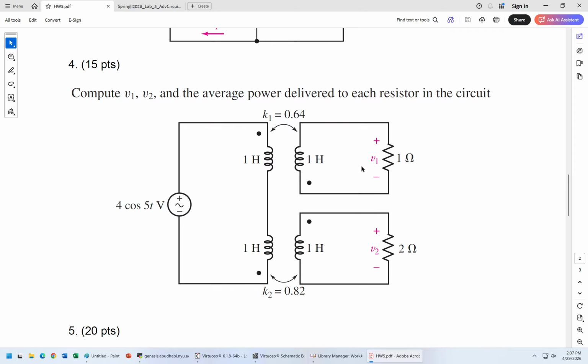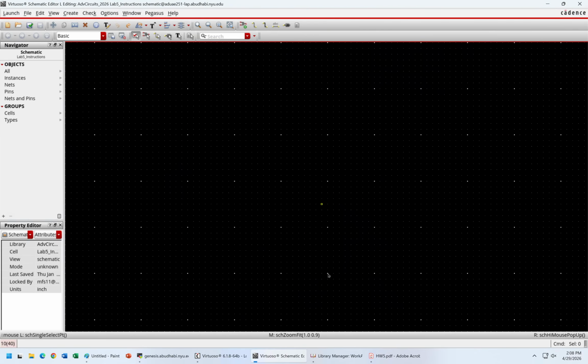You will see how we will always be finding out the voltage across a component instead of putting a lot of grounds, because grounds, as I've been telling you guys, are kind of short-circuiting some of the nodes, which are called reference. You will also see how inductors, when defined in the form of a mutual inductance or in a transformer situation, how do you define the series resistance with the coil to implement? Otherwise, you will see the errors in your Cadence simulation. So here's the open schematic.